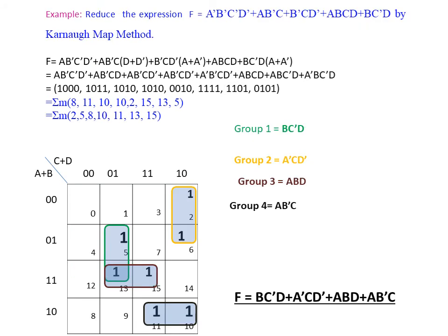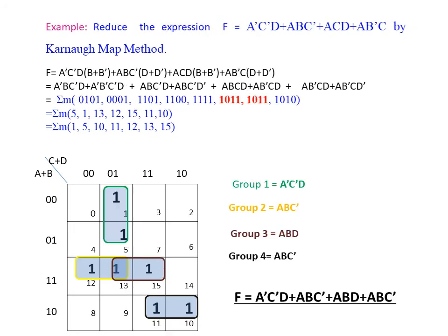The logical expression is given in the question, so we first convert it into decimal form by using the standard SOP form. Then place the ones into the corresponding cells. Here all cells are grouped into two cells grouping. Then we write the expressions for the two cells grouping. Only one variable is eliminated for each min-term.